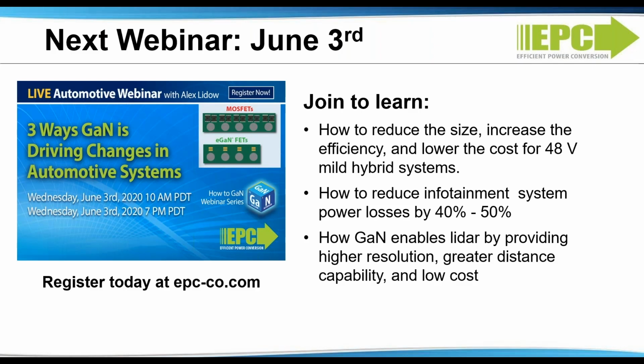Now, the second area is the input capacitance. If you're an LLC running at a megahertz, the input power is actually not inconsequential. And in a MOSFET, it's 5x that of a GaN device. So that can be a very big factor, the CISS.